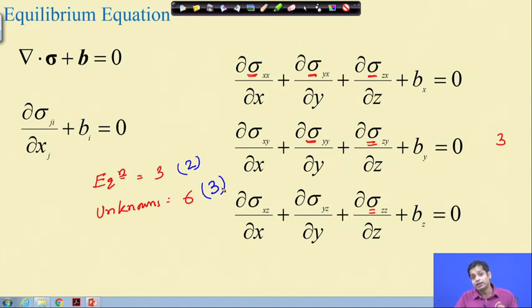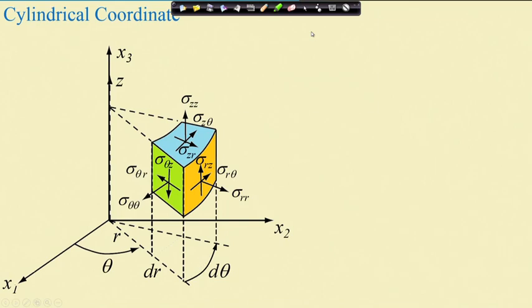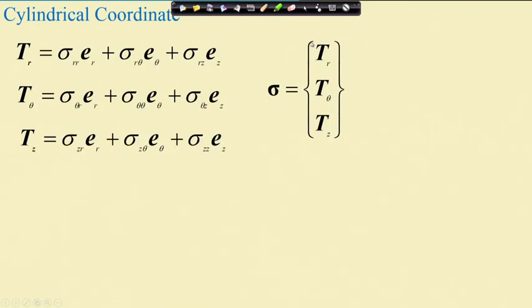Recall in strength of materials, when you analyzed some structure, you applied the equilibrium conditions and found that the equilibrium equations were not enough to analyze the problem completely, so we had another set of equations. We derived another set of equations based on displacement compatibility, and that is the compatibility equation here, the same compatibility equation, but written in terms of strain. That is why it is the strain compatibility relation.